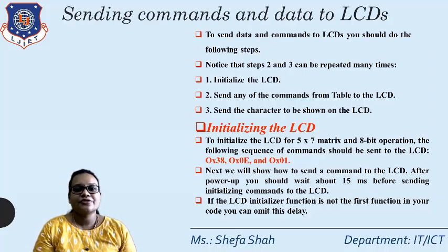So, what are the different steps for sending a command as well as the data to the LCD? As you can see, to send the data and commands to the LCD, you should do the following steps. First, initialize the LCD. So we need to initialize the LCD screen. Then send any of the commands from the command table to the LCD. So different commands are given from the table, in the form of code to the LCD screen